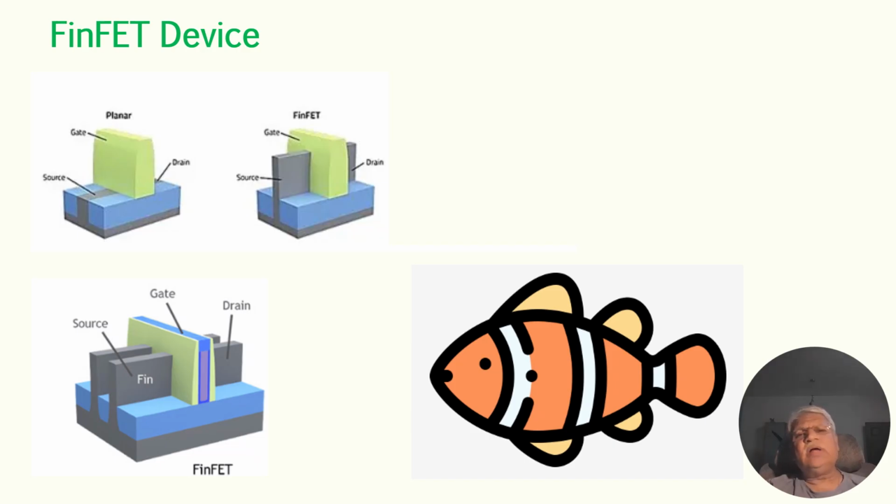Let us also understand one more thing, why we are paying so much money towards EUV lithography tools in sub-nanometer fabrication. As told earlier, the gate pitch, fin pitch, fin height, and fin width all play a crucial role, and fabricating them with extreme accuracy so that yield will be high makes a huge difference.